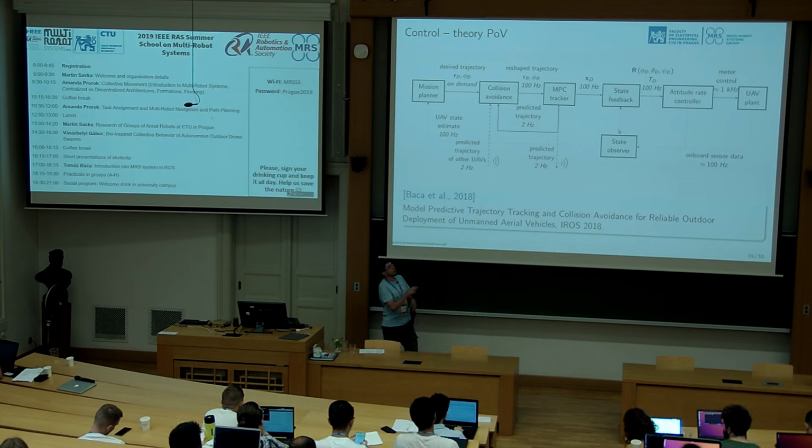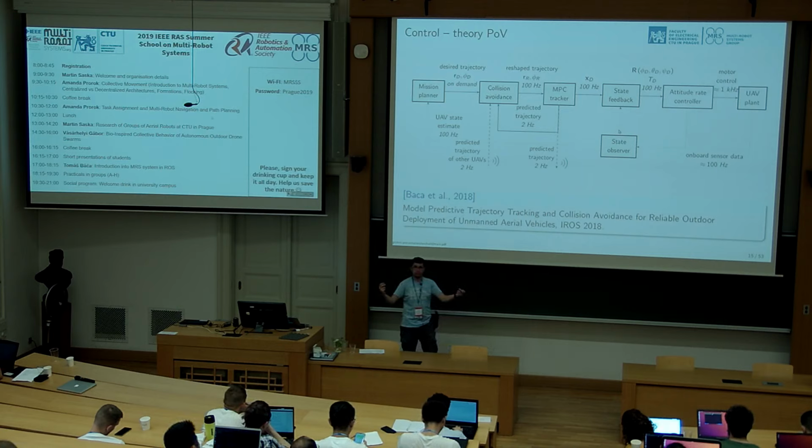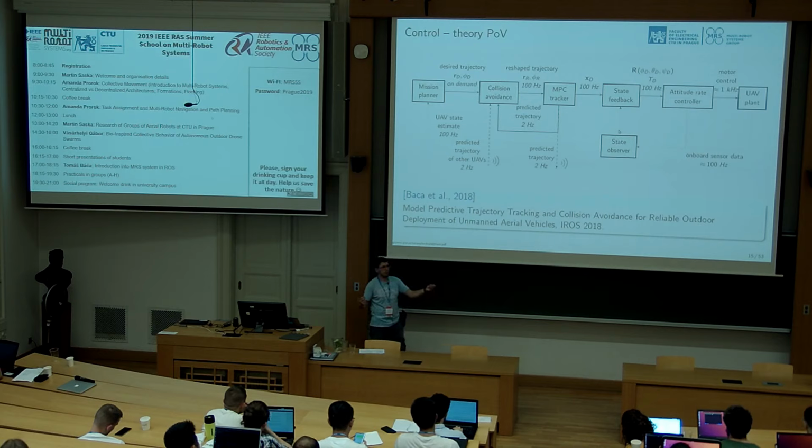So that's what trackers do. Trackers take a high-level reference, let's say, let's fly from 0,0,0 to 10,0,0. And this, which we call a go-to command, is then translated into a series of changes of position, velocity, and acceleration states throughout the time from point A to point B. That's what trackers do.